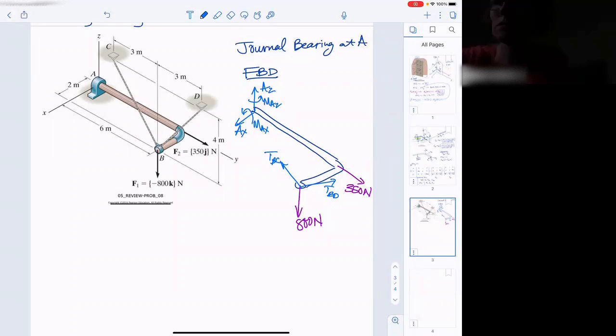If we'd had a pair of journal bearings here, then we wouldn't put any of those unknown reaction moments on there. But looking at my picture, I'm counting two tensions, two reaction forces at the bearing, and two reaction moments at the bearing. So that looks to me like I've got 6 unknowns, and it's a 3-dimensional problem, so I can write 6 equations. So we should be able to solve it.